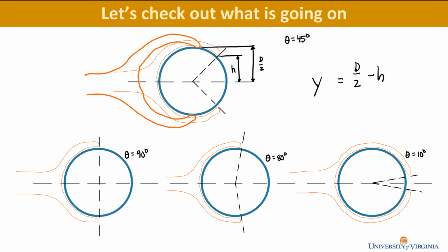So I have our 3 different examples on the bottom. And the deflection, if we had theta set to 90, is going to be 0 because the part is designed such that the prongs never have to extend in order to insert it or pull it out. It never wraps past that midpoint of the rod that you're trying to wrap it around. So the max deflection is 0.